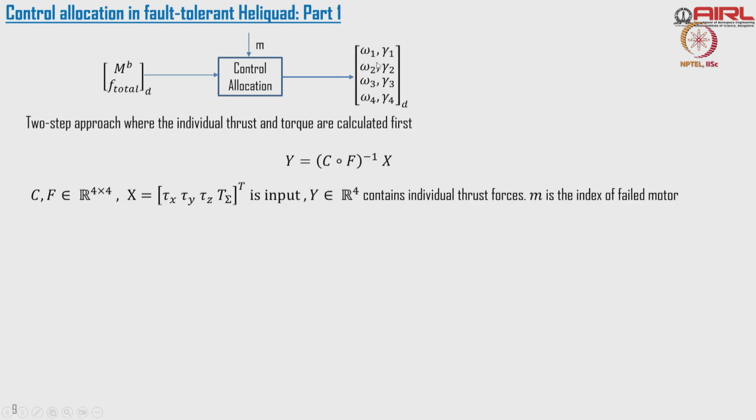So I will get two values, RPM and pitch. If you look at a normal quadcopter, it will give only RPM, if you remember from our earlier slide. Here is a variable pitch quadcopter. I can change the pitch of the propeller as well as the RPM. So I have two values for all 4 motor and propeller systems.